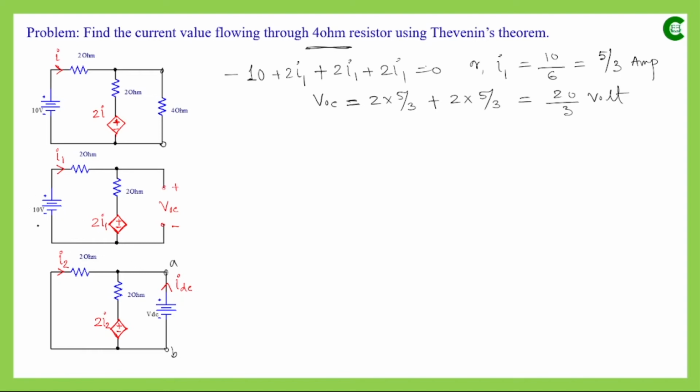So here we had an independent voltage source, so we have shorted that path, and since we have removed that, we have deactivated that voltage source, that means the current value that will flow through this 2 ohm resistor will again change. So this time I am assuming that the current is I2, and accordingly the value of this voltage source will change, and this will be 2I2.